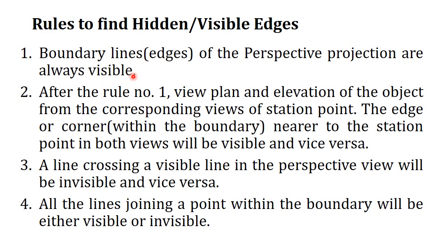After drawing all the boundary lines as visible edges, view the top view and front view of the object from the corresponding views of the station point. That is, from the top view of the station point, view the top view of the object, and from the front view of the station point, view the front view of the object.